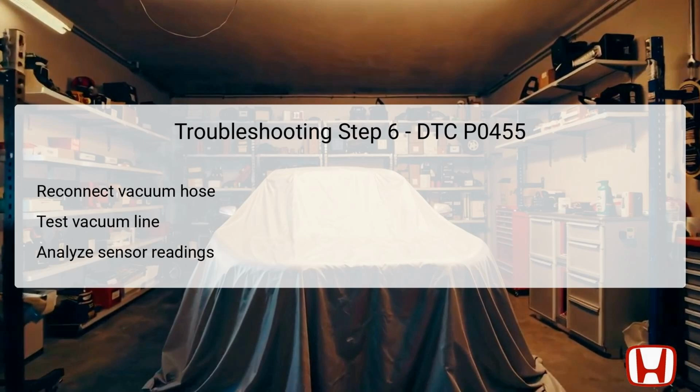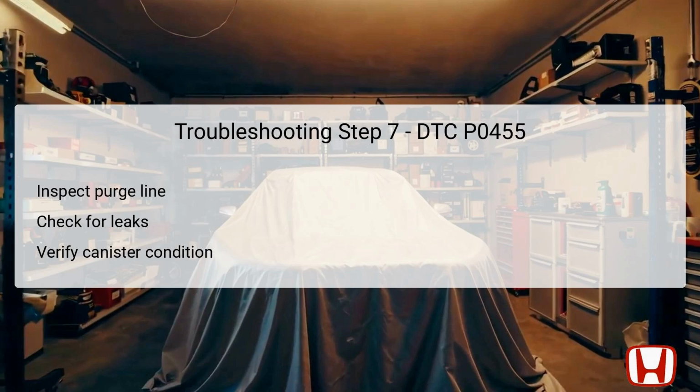If the voltage reading increases more than 0.2 volts during the test, the pathway is likely compromised. If not, the EVAP canister purge line is functioning correctly, which means that replacement of the EVAP canister purge valve is warranted.